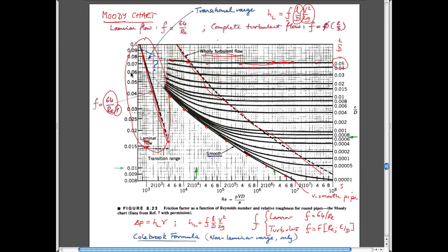So the important regimes are here where it's laminar, where the friction factor changes with the velocity directly. Here where it's turbulent, where the friction factor is constant. And of course, the value where you get transition from one to the other is indexed by the relative magnitude of the Reynolds number. And so the final parting shot to notice is that as you have very rough walls,